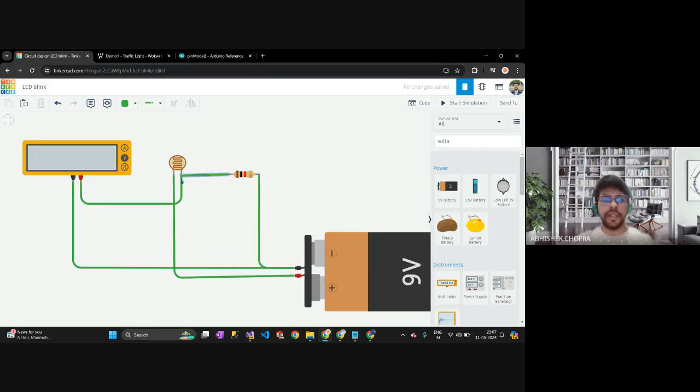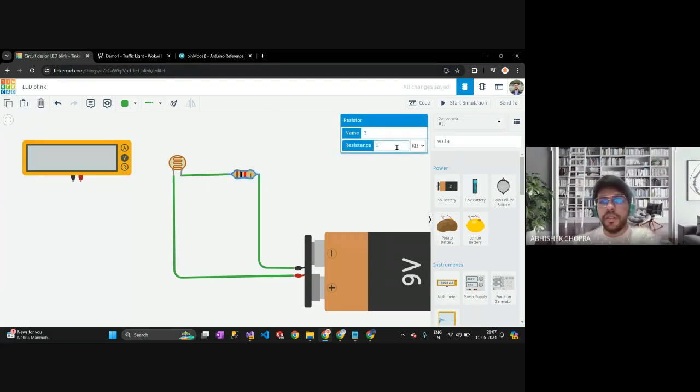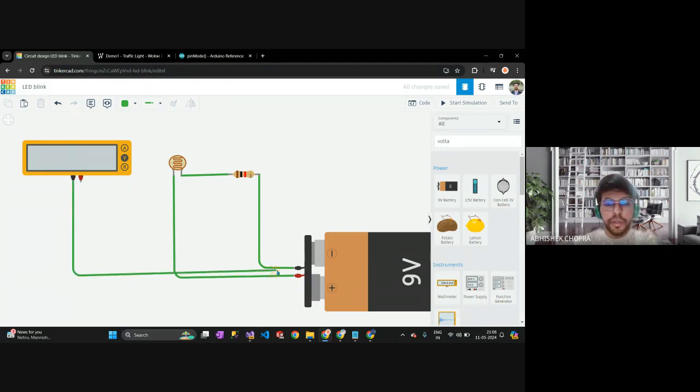So we'll see what's happening here. I'll go with the circuit once again, the multimeter circuit. I took a resistor of 1 kilo ohm. I could take 10 also. 1 to 10 is measurable. So I'm just trying to measure the potential difference within these points, right? For the multimeter, I connected this to ground only. We could have a common ground. Okay, and the point we want to measure the voltage at is this point, right?